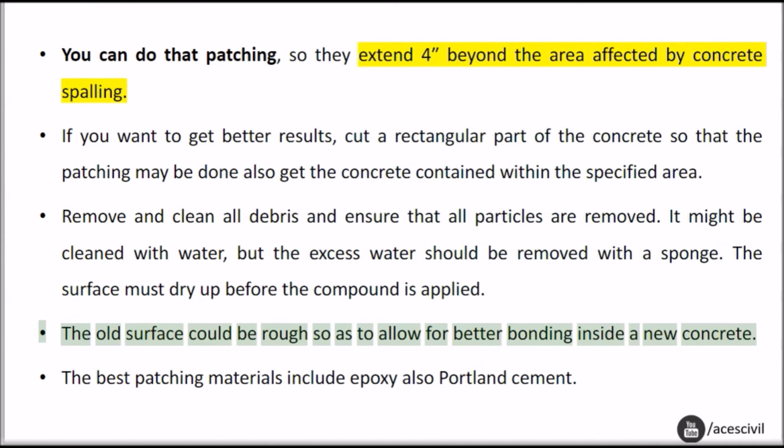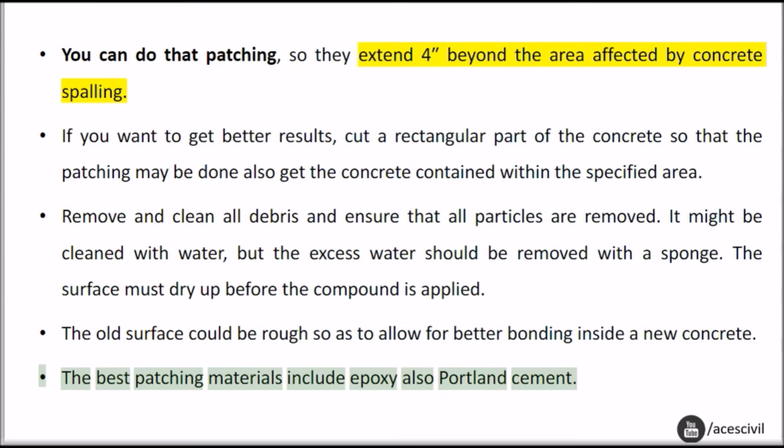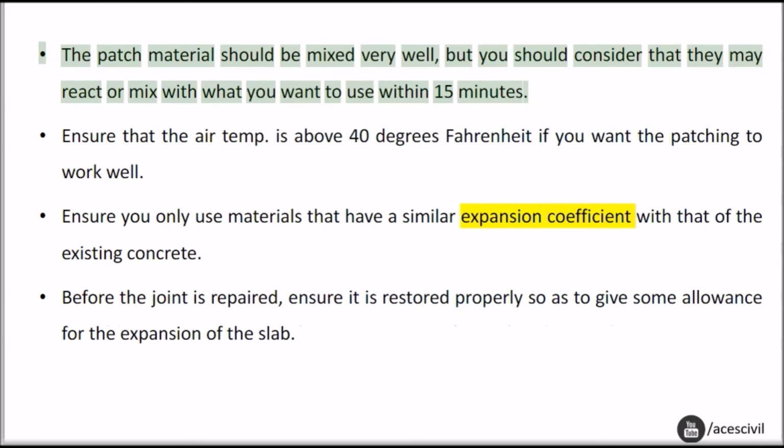The old surface could be roughened so as to allow for better bonding with the new concrete. The best patching materials include epoxy and Portland cement. The patch material should be mixed very well, but you should consider that it may react, so use what you mix within 15 minutes.